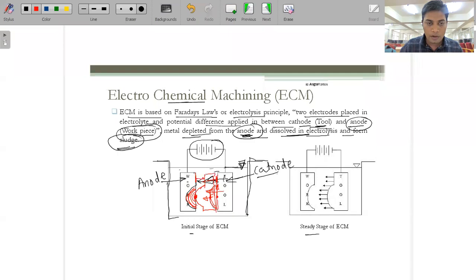Now if this complete part is formed and you still keep moving this tool towards the workpiece side, the material will start removing from this cross sectional area, because the minimum gap is no longer maintained, it is decreasing as we move the tool. So we have to keep in mind, once the job is completed, move the tool away from the workpiece area. Now the material is removed.